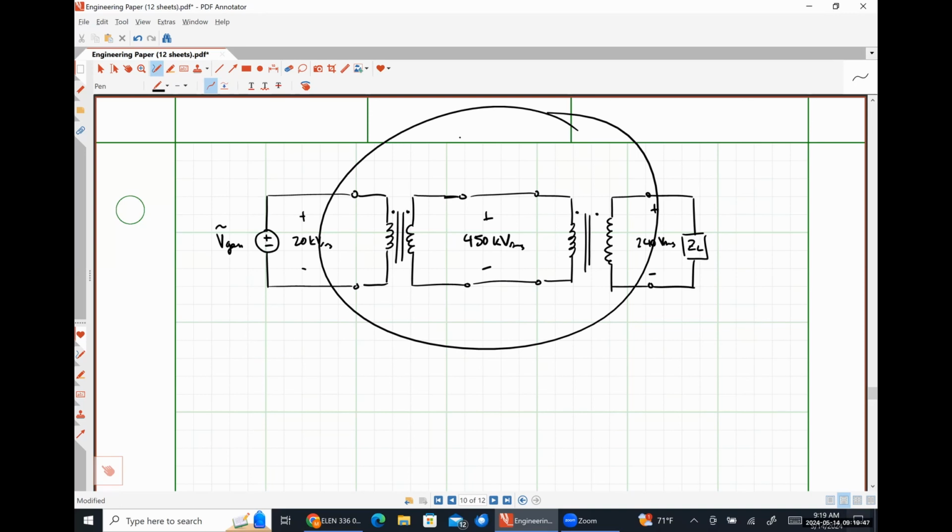So those cables are used to do effectively exactly what you were just talking about. Okay? So you would plug one end of a cable like that into your generator and the other end into an outlet in your home so that you backfeed everything, electricity from your generator into your home. The big problem with that is that if you don't remember to disconnect your main breaker, when somebody's working on the utility lines, you're sending energy to that too, and you could kill a man. So that's why I think anybody who buys a cable like that is an idiot and a potential murderer.